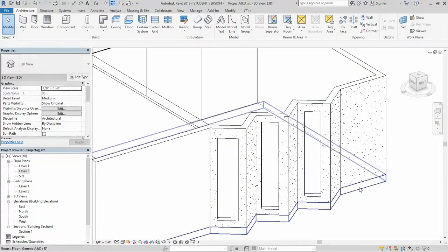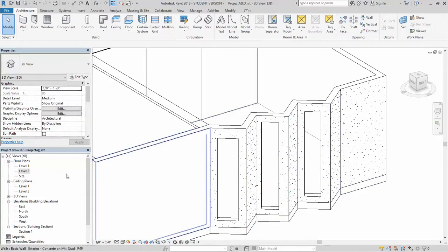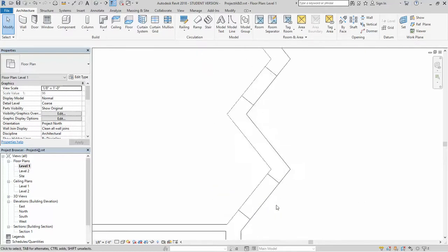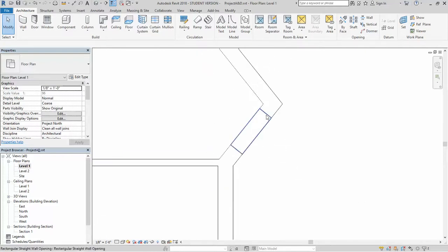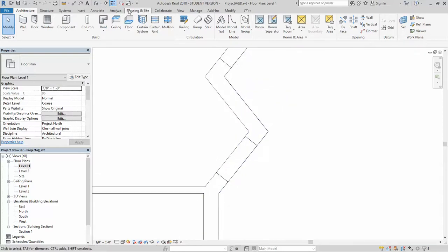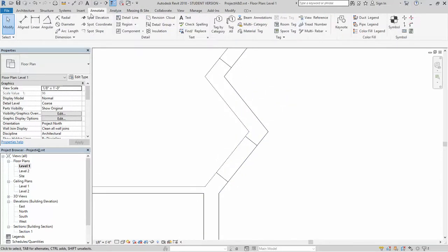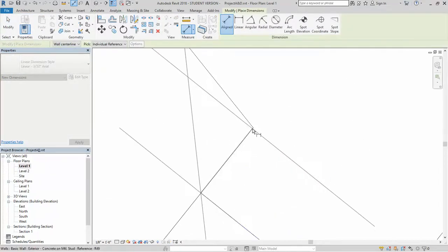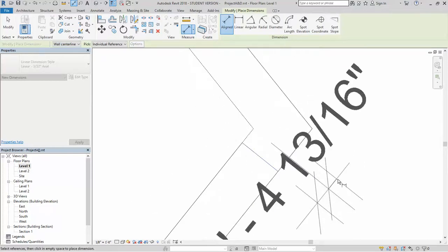Okay. We have to make sure those windows are a proper dimension. How do we do that? Well, we go to level 1 and we look at the cut in plan to understand the relation between the window and the corners of this building. So we can now start using the annotate, align, and you can just select on the line here, it turns blue, and then on this little point it turns a little blue. It's very small, but you can see that.